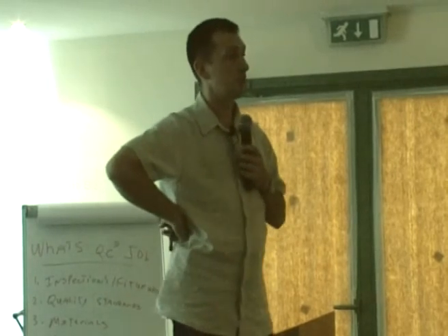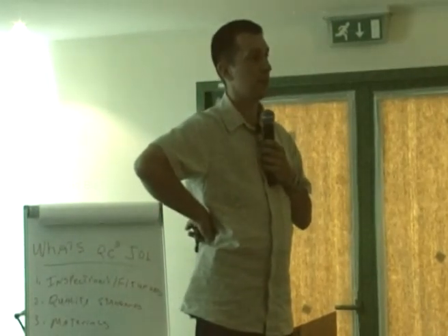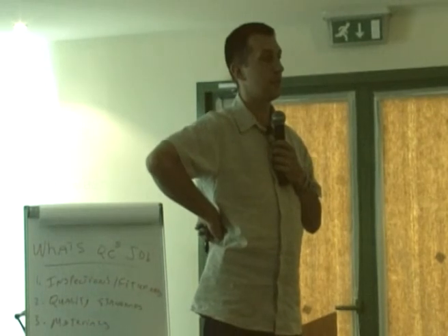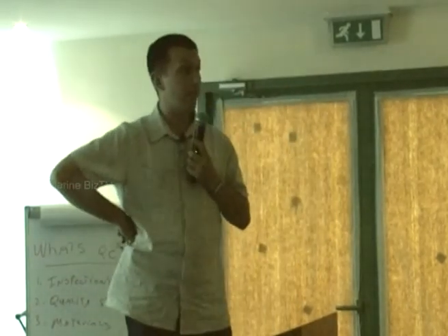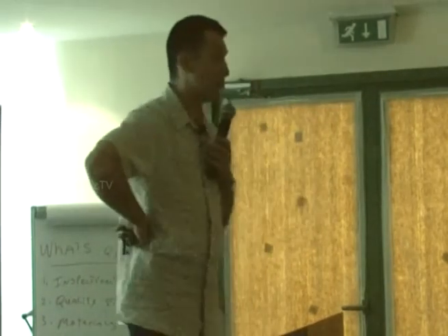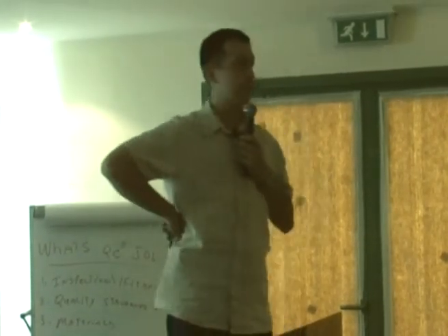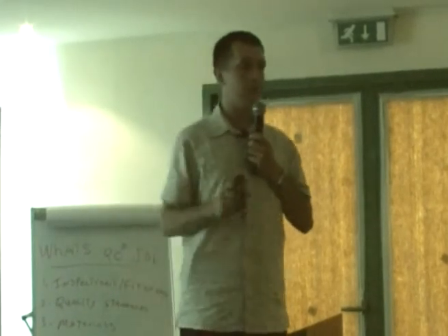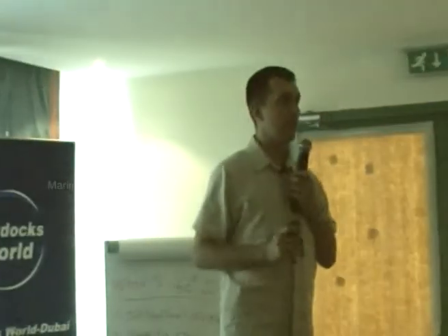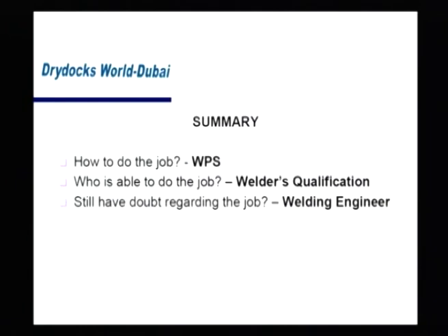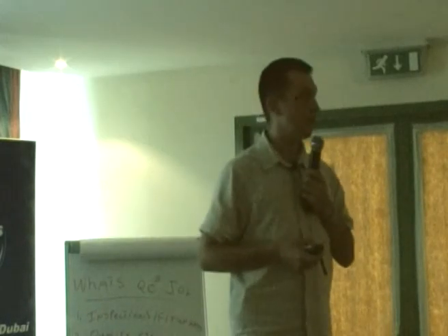Okay. Can you elaborate what we're doing to help the subcontractors with WPSs and their identification cards? Yeah, it's very interesting. What we are trying to do now is to implement basically a qualification cards system, which is going to give you very fast information on what kind of job he is able to do. So it will be a very small laminated card, valid for 6 months. So every time you can check on the job whether he is really qualified for the job or not.